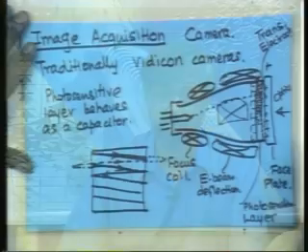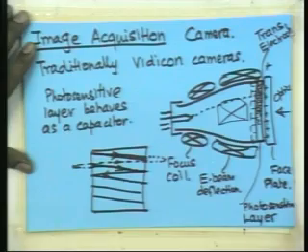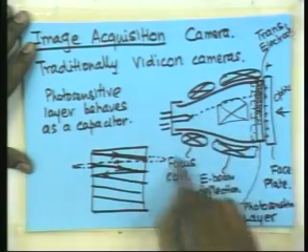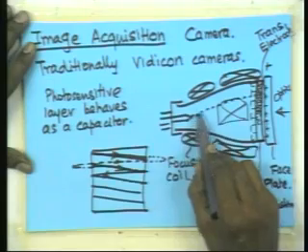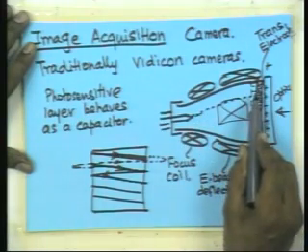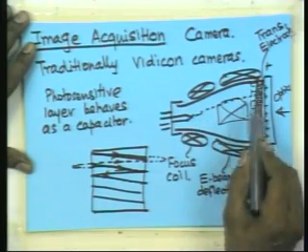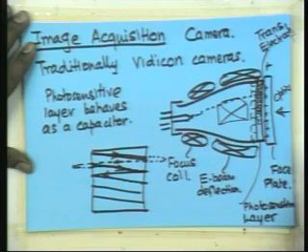Yes, that is if I look from the front here. This is looking from the side, this is the side view. The electrons are coming from inside the tube toward the front, but they are not coming outside the tube, they are remaining inside the tube. But how are they turning? They are turning because of the magnetic field of the deflection coils.